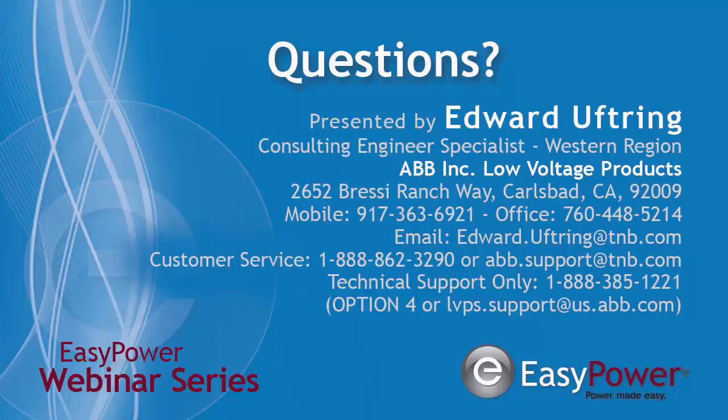The earth fault settings, again, I talked about the LSI curves that you all saw. Our breakers, if you get a hold of our literature, and I can make that available again with emails, I can blast it out. Basically, it's another curve where you can set the rating of it as well as the time delay of it. Generally, you want that as quickly as possible, because if you're leaking current to ground, if you're not getting that current back on the return, that's a dangerous situation. That means it's going to be energizing something it shouldn't be.